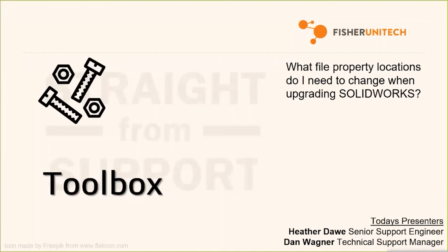You can actually upgrade your toolbox to the new version, and they've added a setting where you can upgrade and make a copy of the old one. So if you're still working in 2017, but you also want to work in 2018 or 2019, you can upgrade the toolbox and have an old 2017 or 2018 toolbox sticking around. That way people can still work in the older version, but when you go to upgrade, you want to make sure you use that option to upgrade the toolbox so you don't lose any of those changes you've made to your custom toolbox.